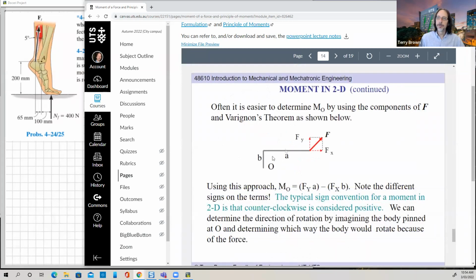Often what happens in structural analysis problems is that you tend to know perpendicular distances from the given dimensions of the structure that you're analysing. And often the force will be at some angle to that. So here, instead of trying to work out the perpendicular distance, the line of action of this force is down here, and then we need to work out the perpendicular distance here. To find the length of this blue line takes a little bit of trigonometry to work out, right?